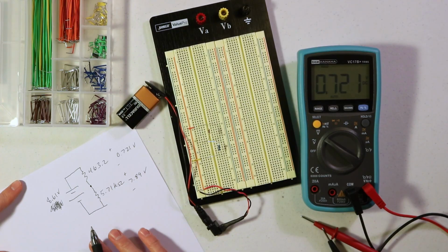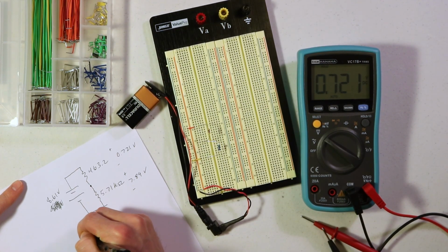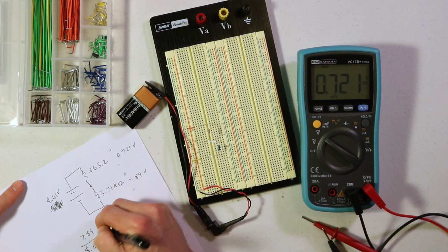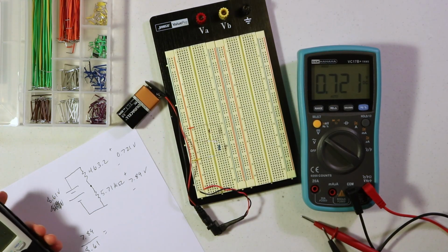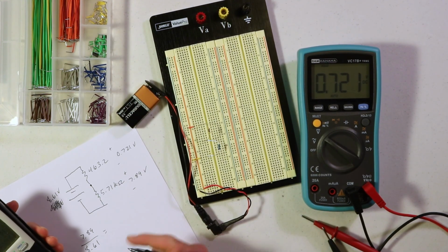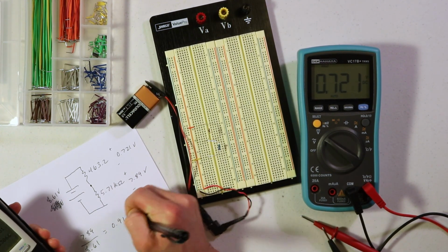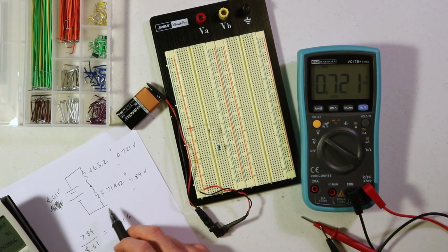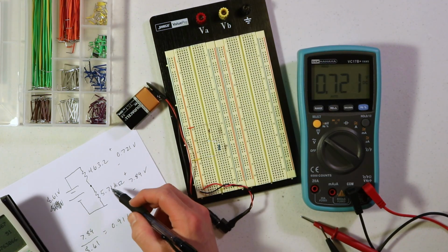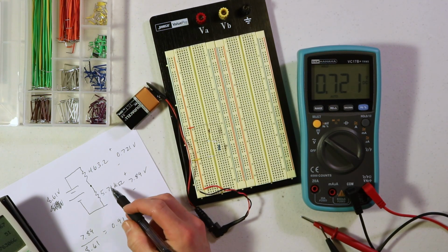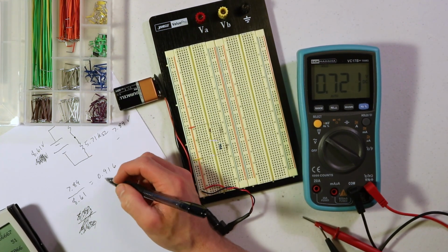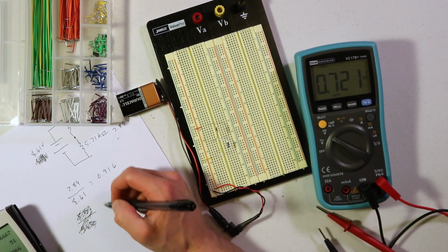So real quick, let's just double check the math on this. So if we take our 7.89 volts and divide by 8.61 volts, the value for that we can calculate. 7.89 divided by 8.61 gives us 0.916, and we can check the same ratio now if we look at the resistor values. So it's going to be equal to the ratio between this resistor over the whole resistance. I'm sorry, the calculation I just did was off the screen, so I'm just going to do that again.